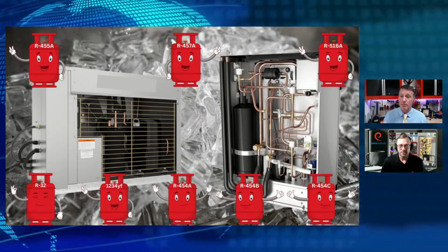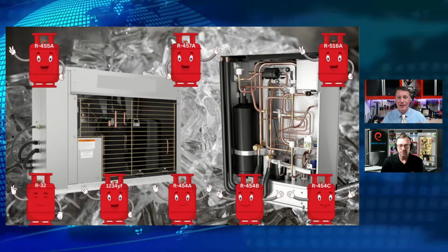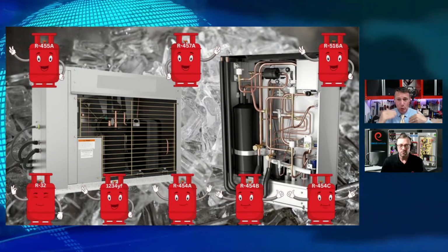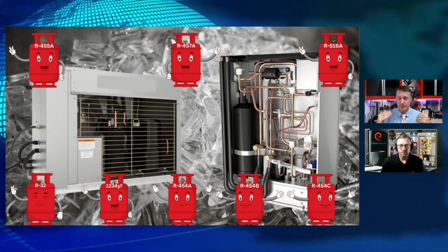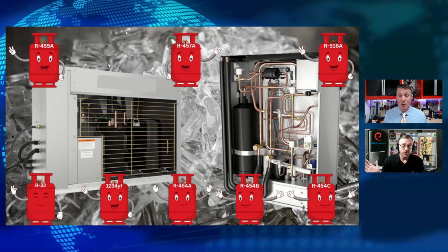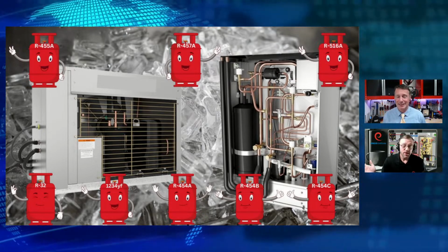But still, we're talking about blended refrigerants, right? We're still talking about adding in 1234YF or R32 or 125, 152. We're talking about blended refrigerants, right? So any of the 400s or 500s are going to be a blend. Your 400s are your zeotropic or near azeotropic, and your 500s are your azeotropic.